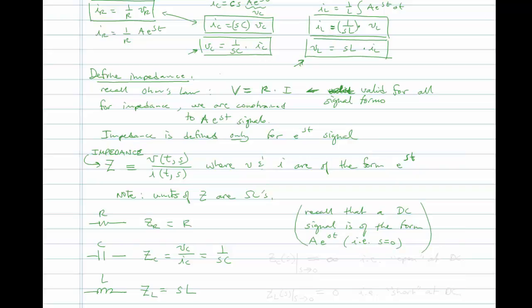So let's check if these impedance expressions for the capacitor and the inductor actually are consistent with what we know. We've been working with capacitors and inductors for a while, so we know that for a DC condition, the capacitor acts as what? As an open, right? If it's open, then its resistance, or its impedance in this case, is going to be infinite, right? An open circuit infinitely impedes current. Regardless of how much voltage you apply across it, no current will flow.